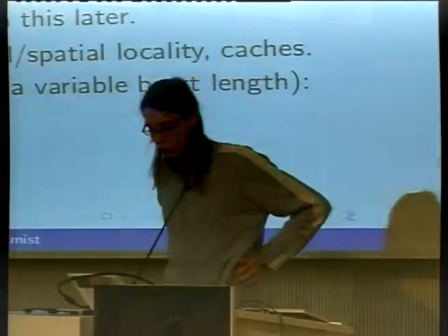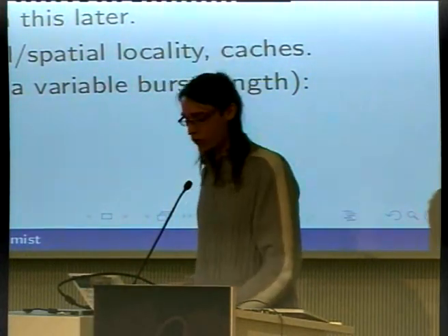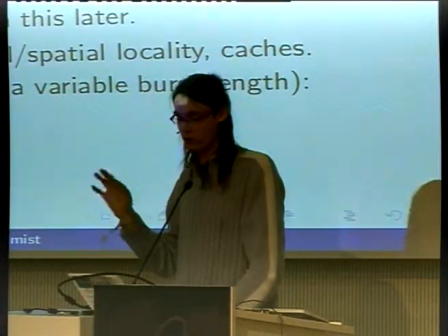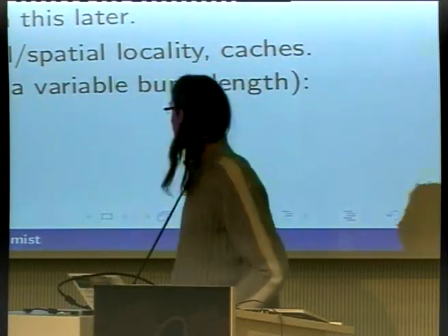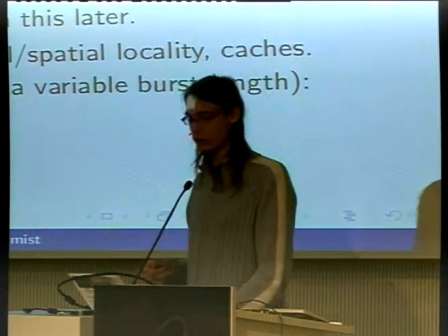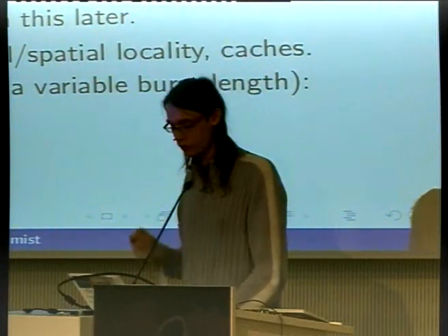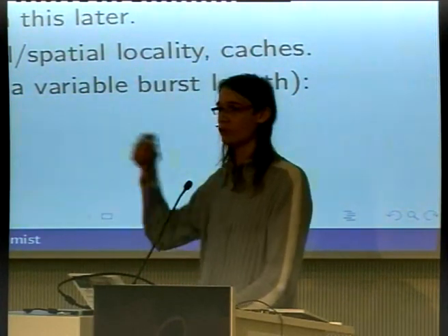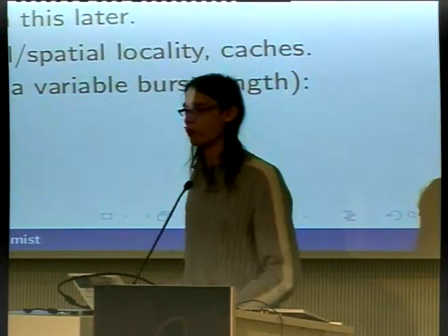For software, you can use caches, and caches work with the principle of temporal and spatial locality, which means that when you are accessing a word of data, you are likely to access in the next milliseconds the words which are nearby. So you can put the complete burst into SRAM, which is on chip, and every time the software requires a word, you search this cache, and if it's in the cache, you can get it in one cycle. Otherwise, you have to fetch from the main memory. And in the cache, you always store the complete burst every time you get it from the memory controller.